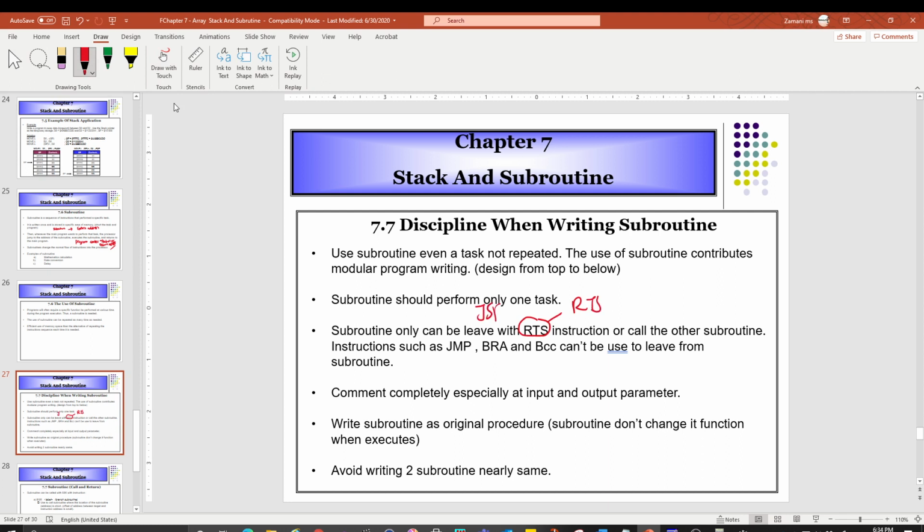So for jump to subroutine or branch to subroutine, you must have the return to subroutine. If you jump or branch with BCC, you are not going to use RTS, because it doesn't matter. But for this one, you must know that it needs the return address and this command to go back to your program. Go back to the program control video to get the answers on that.